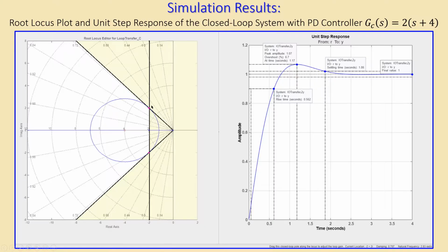Now, if I look at the design point, or the closed-loop poles, which are given by these pink dots, I have then the following location for them. So let's look at the location. This is the first second order dominant pole. This is the other dominant pole, and it has a location you can see here on the bottom. It is -2 plus 2i. That means actually what we have used for our design point.